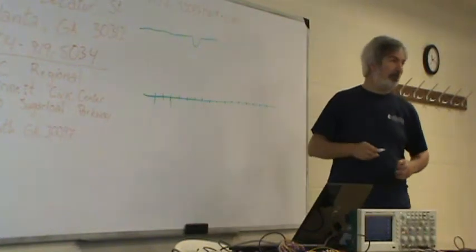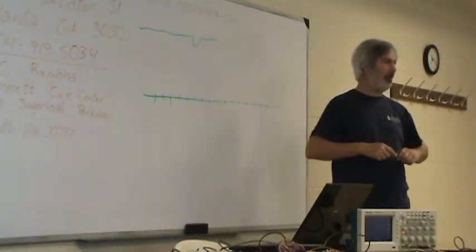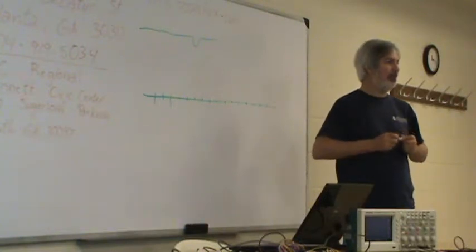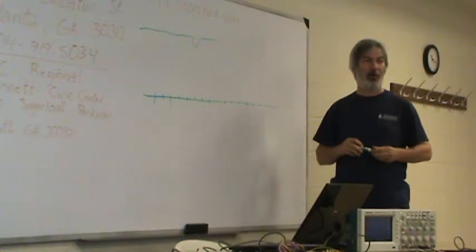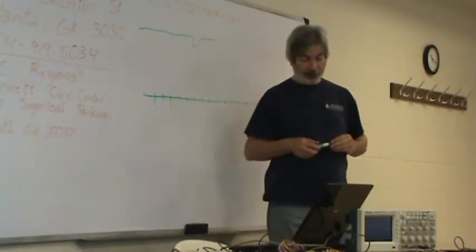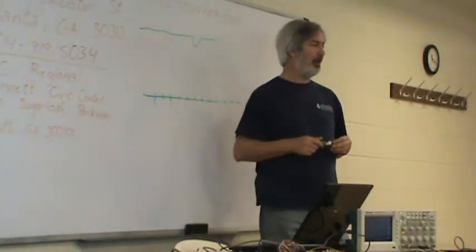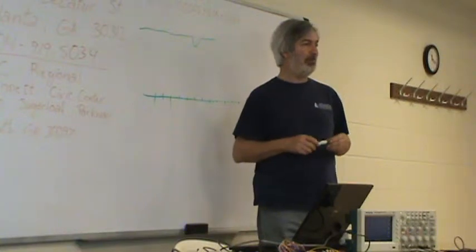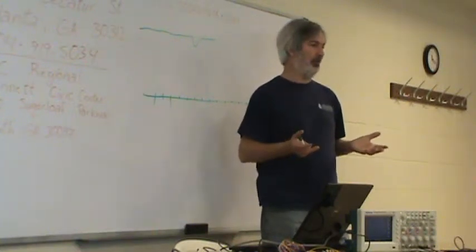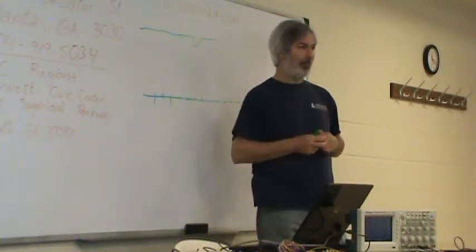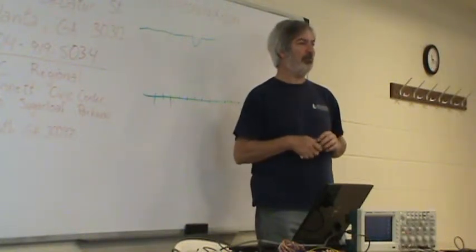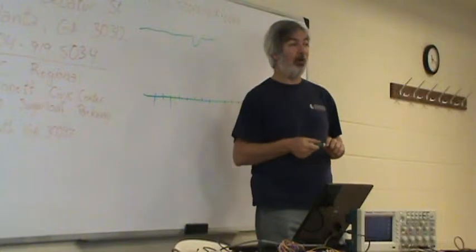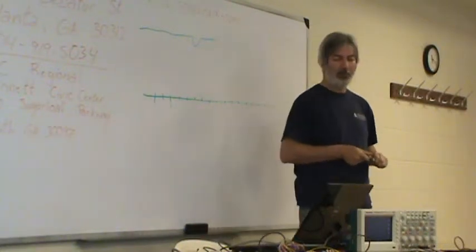And that's one indication that you've got power supply problems. Specifically, that you may very well be pulling more current than your supply will provide. That's something that is very hard to catch in some cases because it only happens occasionally. And everybody that's done any significant troubleshooting very quickly discovers that those problems that happen every now and then are by far the most aggravating.